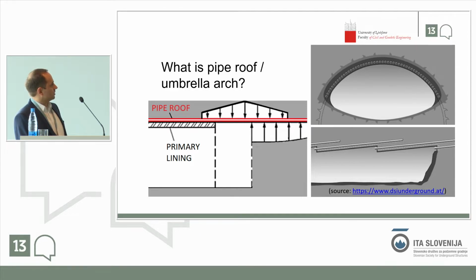And the result of this load transfer is that the displacements, the convergence of the tunnel, are decreased, and also the stability conditions around the face are improved, and also within this region of the excavation, which is temporarily unsupported, the safety conditions for workers improve.